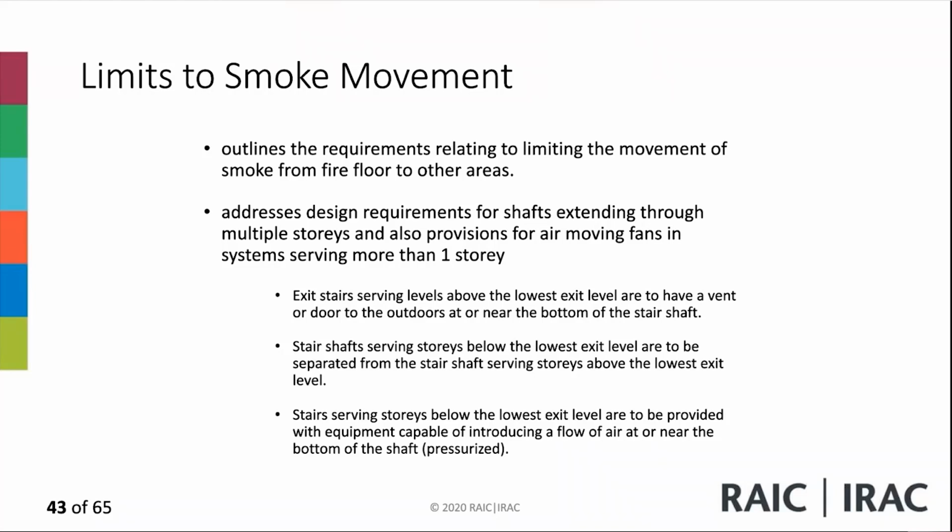Stair shafts serving stories below the lowest exit level are to be separated from the stair shafts serving stories above the lowest exit level. So these are all different protection approaches that are cumulative and add to the protection of high buildings from smoke.